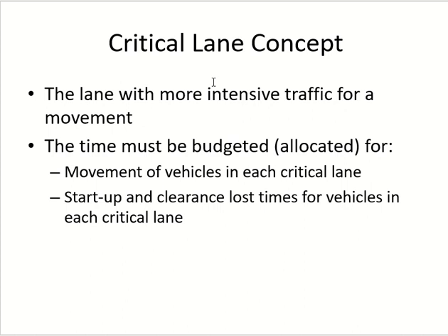The right hand side lane, right? That lane may actually have less volume, but because of the heavy vehicles, it needs more time. So that may become your critical lane. Got it? So critical lane doesn't mean the one with the highest number. The critical lane means the one which needs more time. Got it? Clear? And everything is according to the critical lane then.